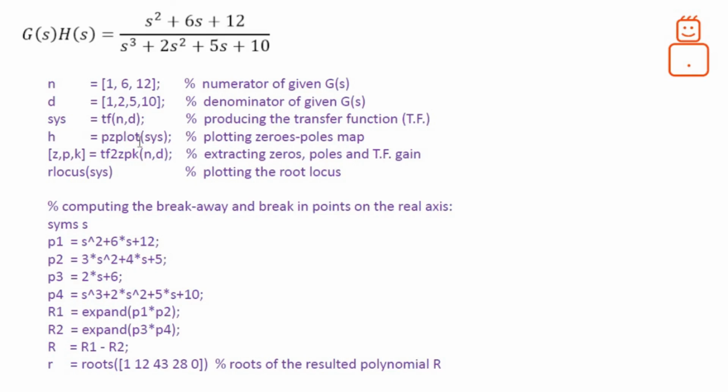You may try to plot the zeros and poles. You can use this command here, or you can also use this rlocus command to draw the final root locus. For the computation of breakaway and break-in points, I already gave this piece of code in the slides when we computed the break-in and breakaway points in the second step.